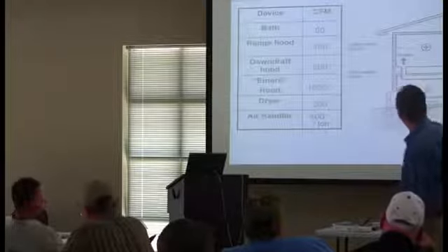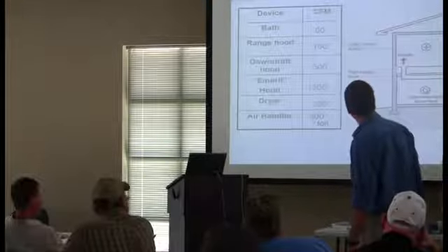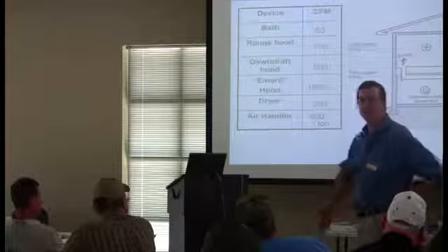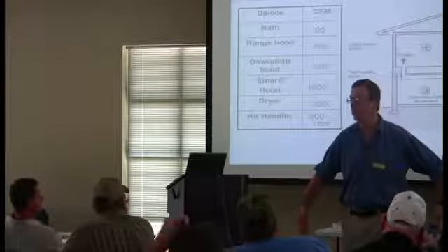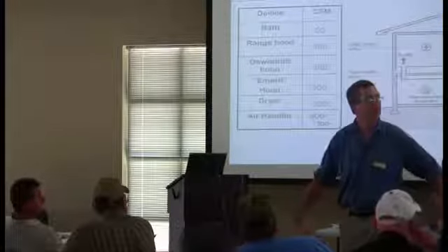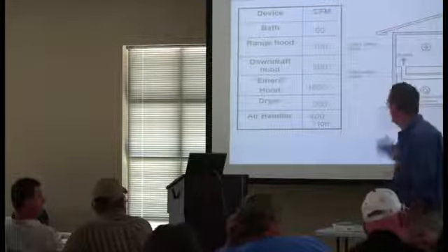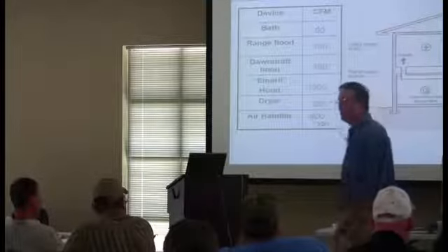So Roxanne, turn it on over here, and she turns on the air handler. It's on, but you notice the flaps on the doors are still pretty much hanging down. So what would you say the pressure on this house is? Positive, negative, or neutral? Same amount of air out equals same amount of air in. The pressure's not out of whack. So why is this even listed up here? Why do we care?